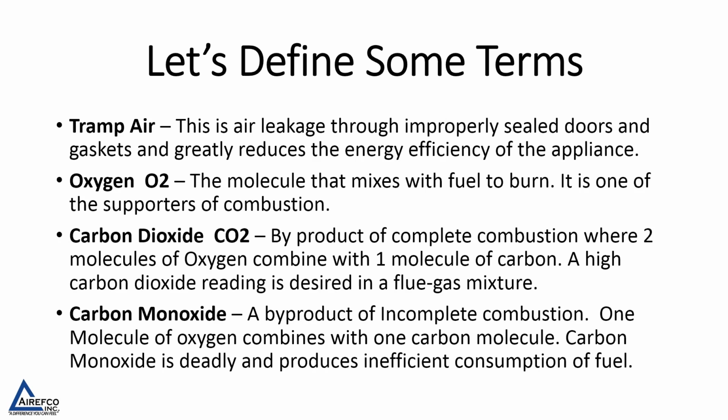Tramp air is air leakage through improperly sealed doors and gaskets and greatly reduces the energy efficiency of the appliance. Oxygen, O2, is the molecule that mixes with fuel to burn. It is one of the supporters of combustion. Carbon dioxide, CO2, is a byproduct of complete combustion where two molecules of oxygen combine with one molecule of carbon.